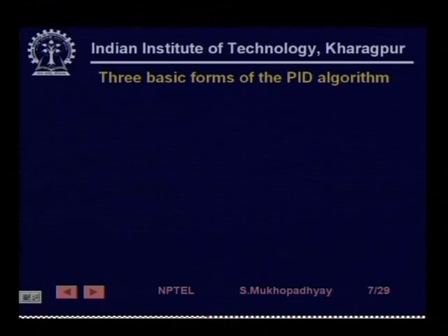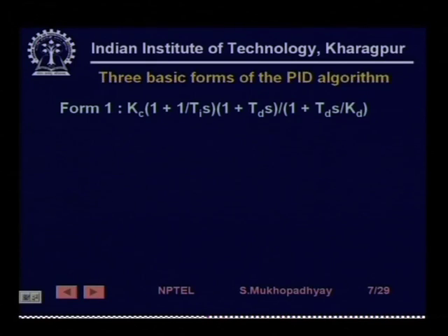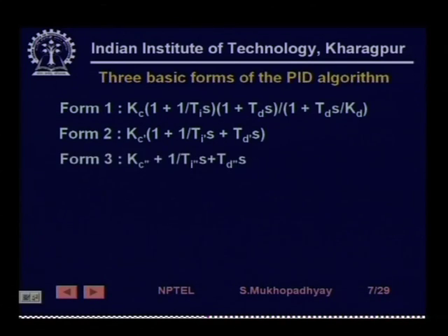Having seen that, let us come to this point: what is the PID controller and what is the interpretation of its gains. It turns out that there are several forms of the PID equation which are in use in the industry today. So, for example, you have this form, which I call form 1. You have the other form which is form 2, which is probably the most popular in textbooks, and form 3 which is an abstract control systems kind of form,